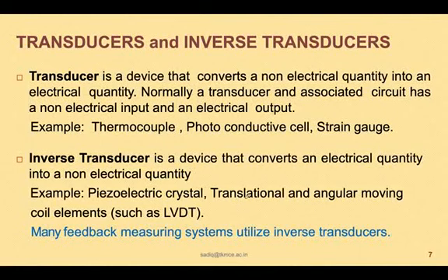Then the translational and angular moving coils inside the LVDT. We have seen in the previous case where there was a core that is moving inside a coil. Actually, the movement is a non-electrical signal, whereas the output obtained from the coil is an electrical signal. That is an inverse transducer. Many feedback measuring systems, including the potentiometers or the synchros, etc., utilize the inverse transducing principle.